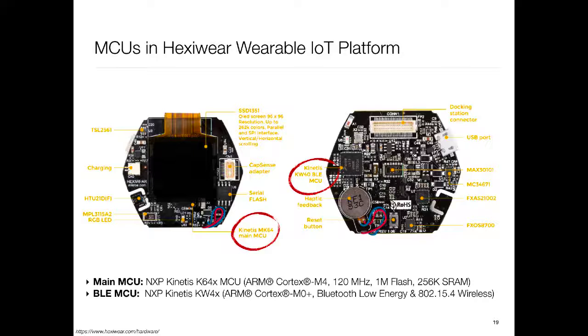And then on the reverse side, they have support for Bluetooth Low Energy. That's the same Bluetooth which your phones use to talk to a whole bunch of common Bluetooth peripherals, and it has its own MCU. Bluetooth is a fairly complicated protocol under the hood, so usually Bluetooth radios come with their own little processor, and then through a serial link you talk to the main processor.